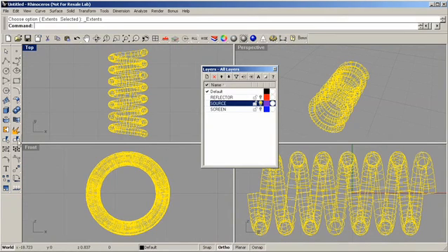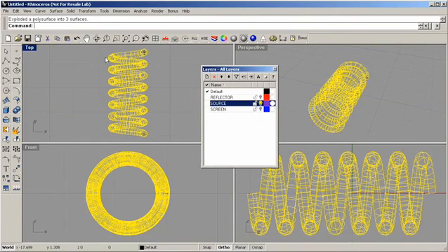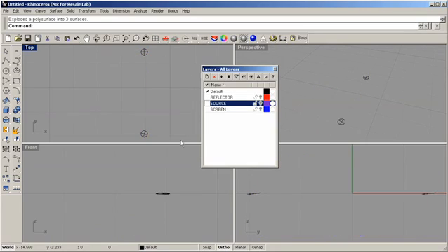Now I'm going to do an explode on this object. And I'm going to place the helical portion of that object into the source layer, leaving the 2 end caps. Now the end caps will not be specified as emitting surfaces. If we want to include those in the ASAP model, we can, and will have very little effect on the analysis result. At this point, however, what I would normally do is just delete these guys.